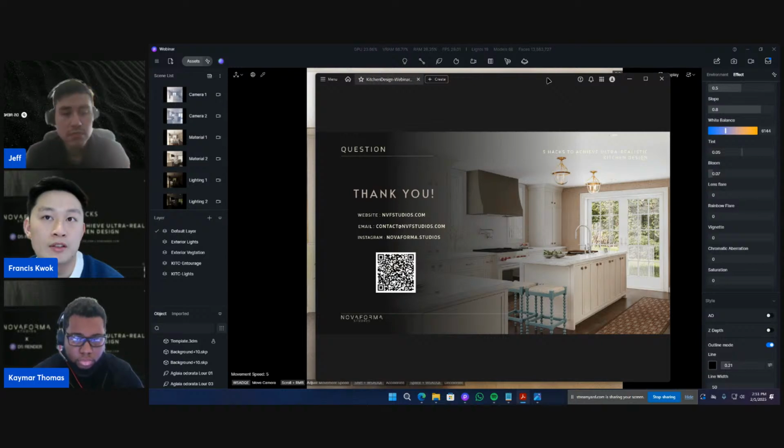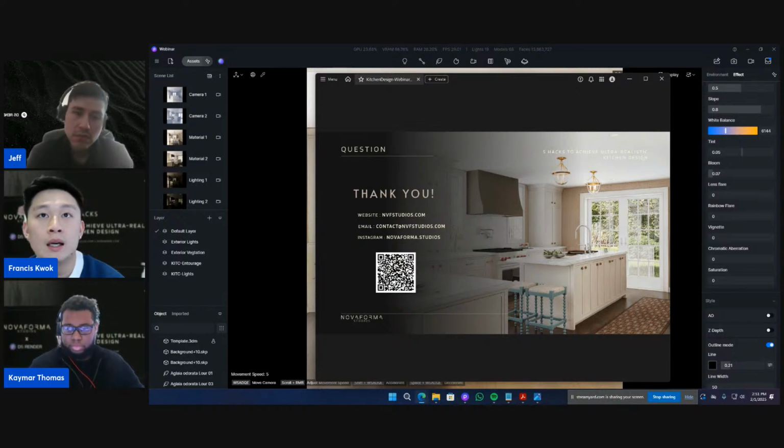So if you're doing a live sync and you're trying to get the exact camera location for the view where you want it, the heavier the Rhino file, the more lag you're going to get while you're running Rhino and D5. By putting it into D5, it's a lot lighter on both files in general.